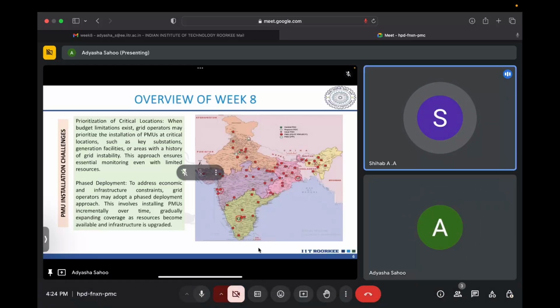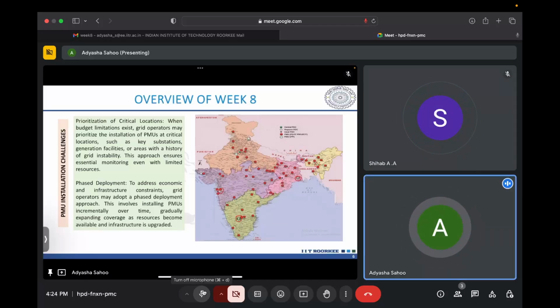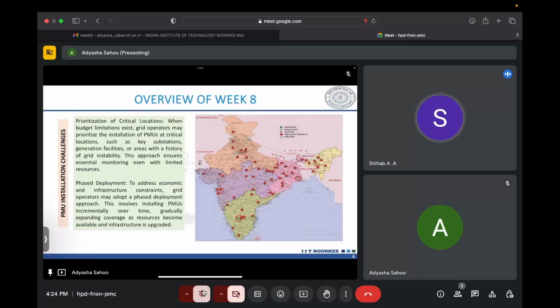This PMU and the RTU. You need the PMU and you need the RTUs for managing the data that is coming from the PMUs. So they will add to the infrastructure once again, where you will have the PDCs and everything, phasor data concentrators and different equipment.